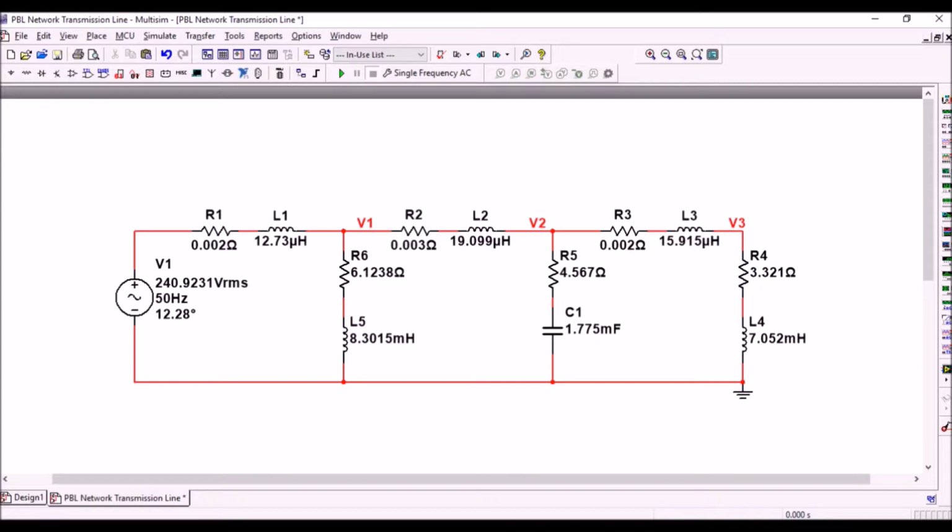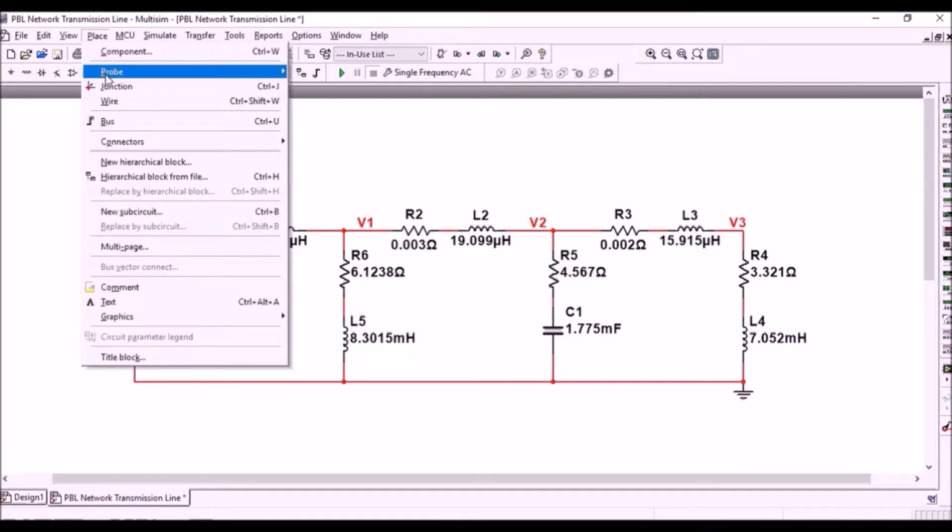First of all, configure all the circuit as drawn during the calculation. Make sure all the components are placed properly. Second, measure the first parameter, which is current in each load and total current. Place all the current probes at each load.